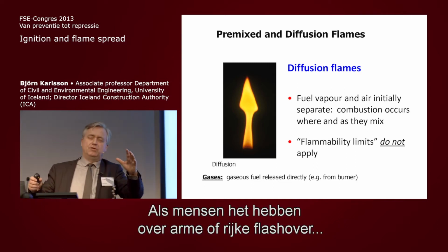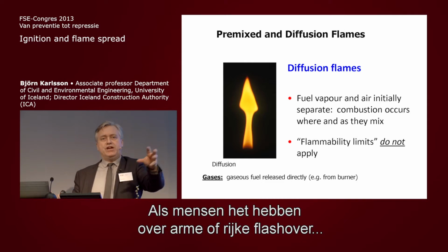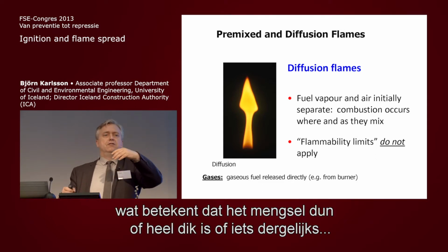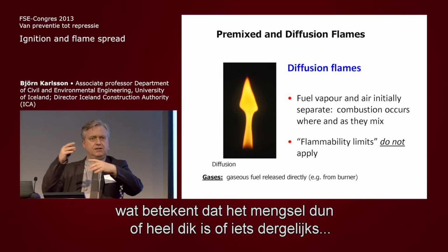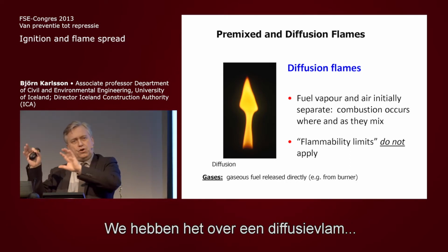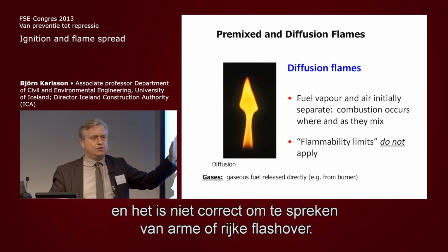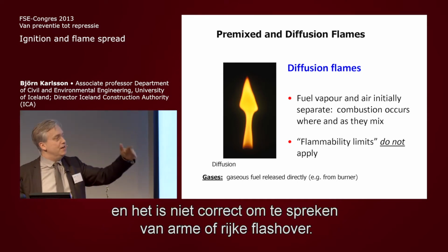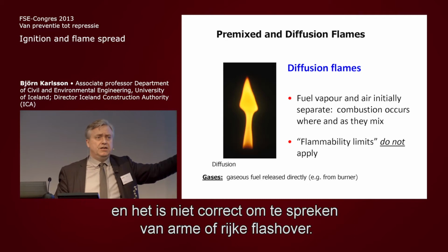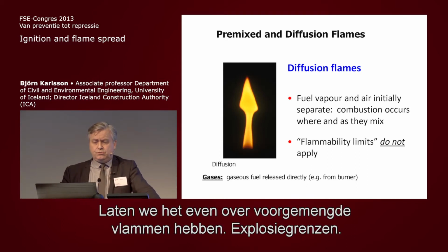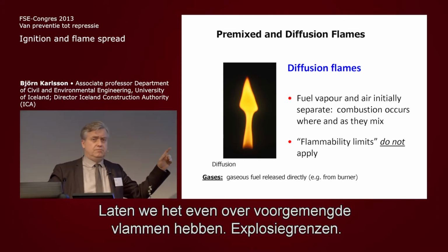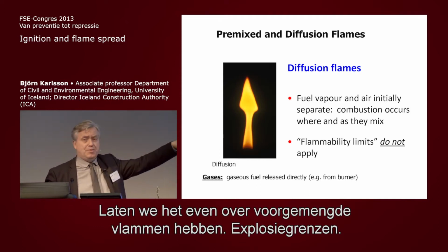Therefore, when people talk about lean flashover or rich flashover, meaning that the mixture is thin or very thick, we're talking about a diffusion flame, and it's not quite right to talk about lean and rich flashover, because in essence it's a diffusion flame that we're talking about. So let's talk about premixed flames a little bit. Let's talk about these things called flammability limits.